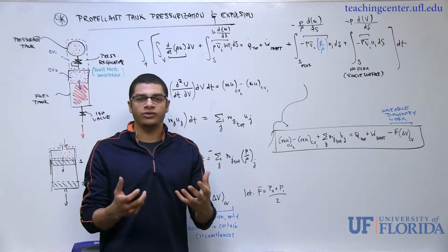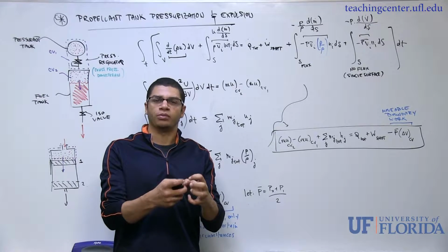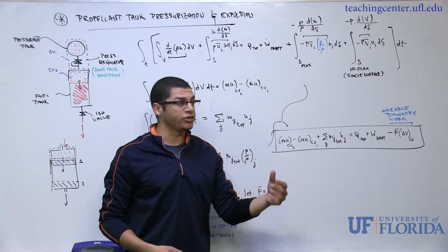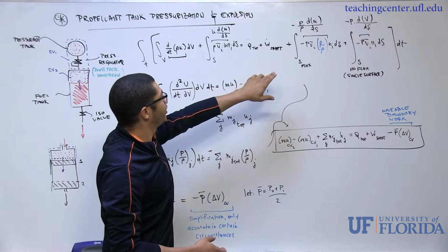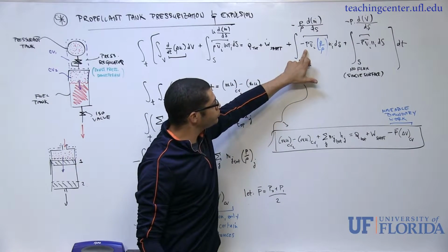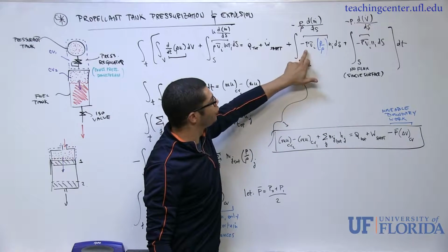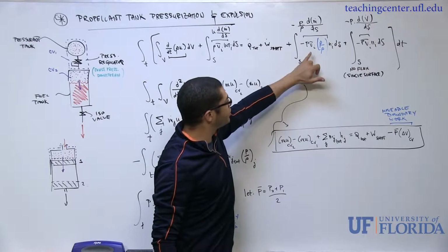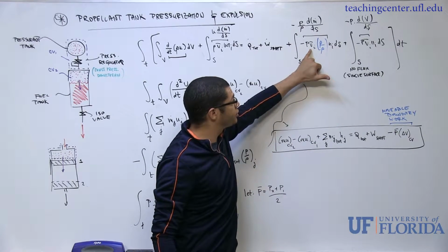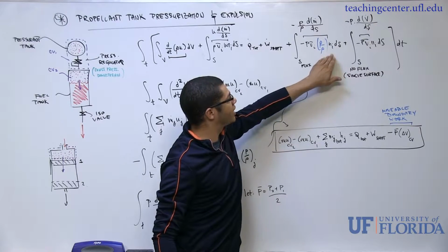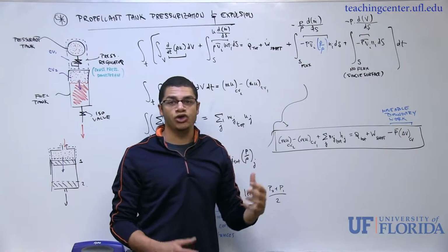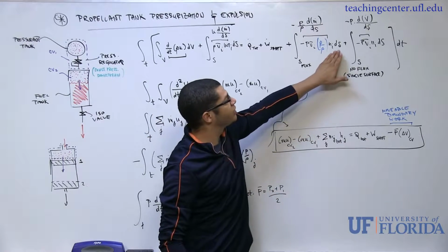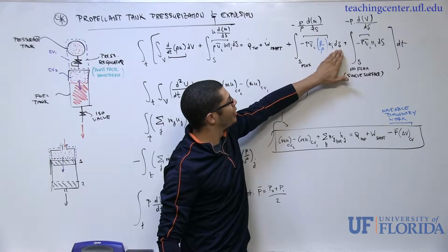And it comes into being by simply the product of pressure and a displaced volume, and this has the units of energy. And this is essentially what this is right here. Again, this is the pressure acting at the boundary of our control volume. There could be a number of discrete locations; I'll get into that in a minute. This is, say, the velocity of the fluid at that interface. Let me skip over this term for a second. This n sub i is just a unit normal vector in order to describe the orientation or geometry of our surface, and this is a differential surface area element.